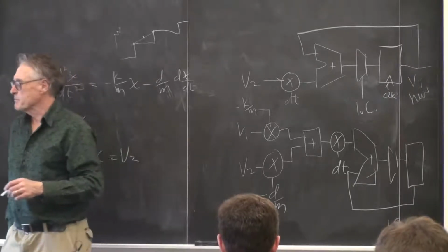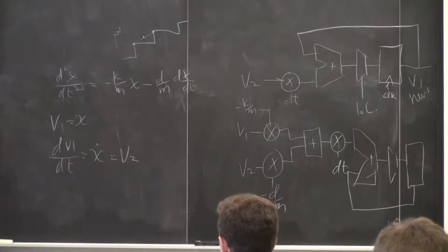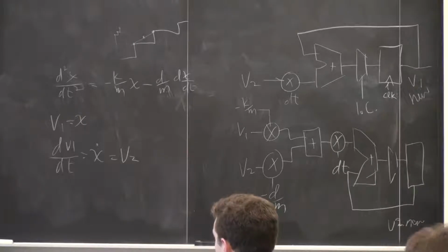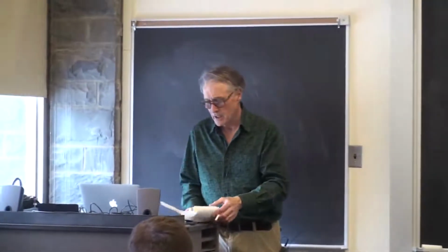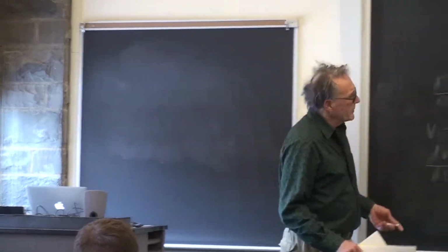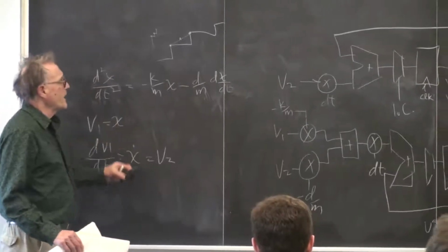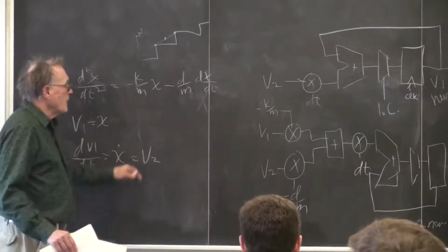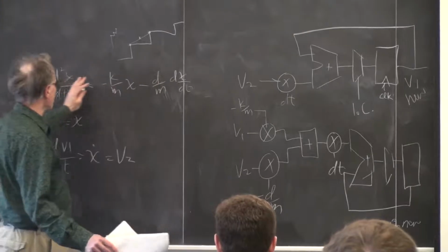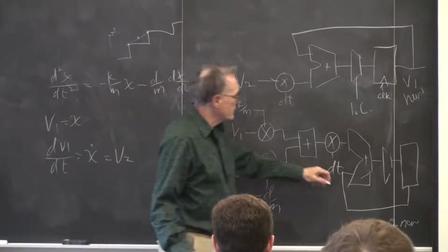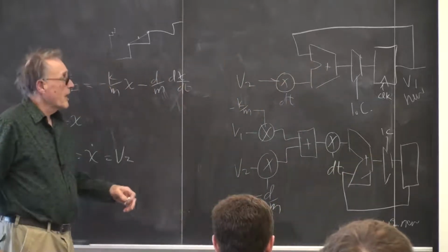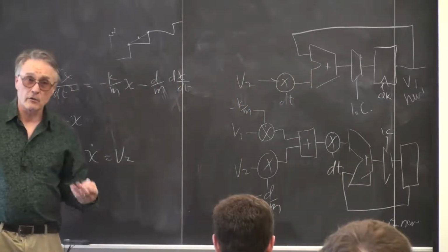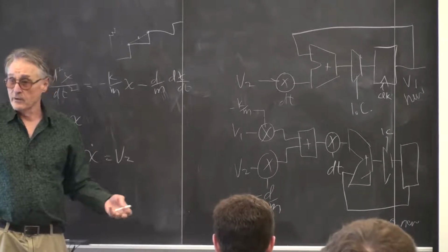I did a couple of experiments to see how fine the step had to be. And it looks like 2 to the -8th or 2 to the -9th is a good value. But what I wanted to do was to try and motivate, if you set up the second order system with the appropriate initial conditions and let it run, and then took the output and put it into the audio codec, you'd get some sine wave frequency.